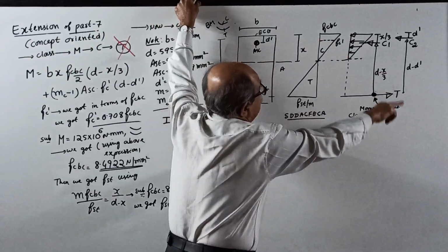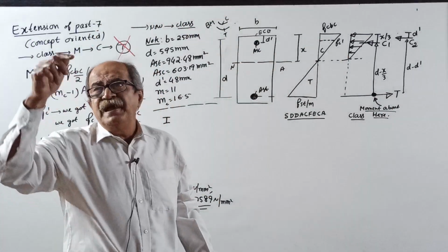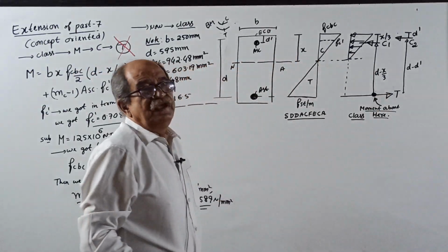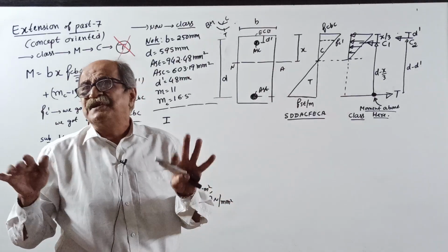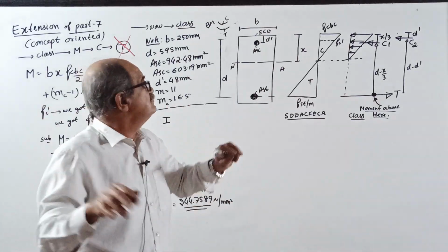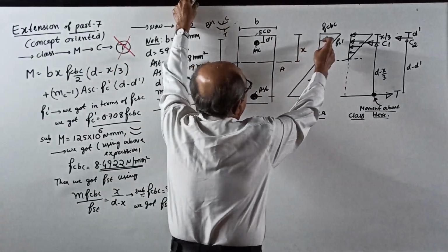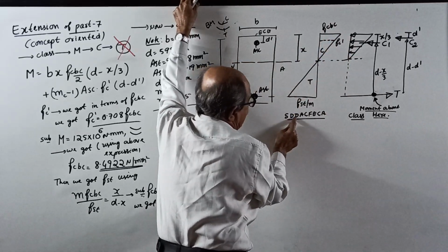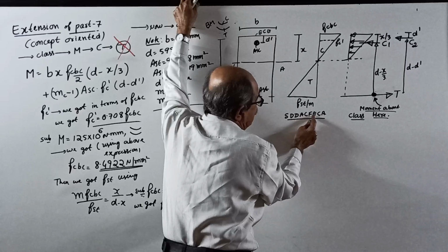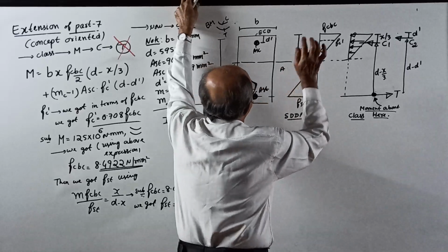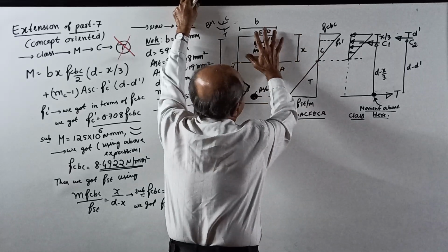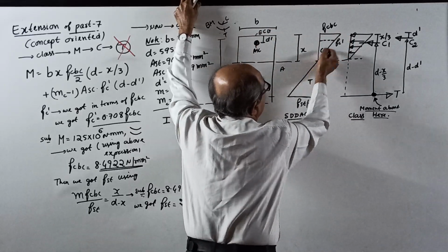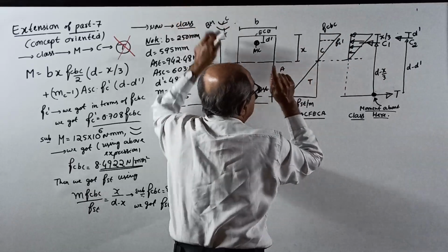Go to the basic derivation. Remember, in my regular batch, I did the basic derivation. If you know the basic concept, you will understand, or you just go through it. Asc, etc. Stress distribution diagram like this. Then the stress distribution diagram across the cross section for equivalent concrete area. Now, from here to here, compression. Stress variation is fcbc here, 0 here, linear variation.